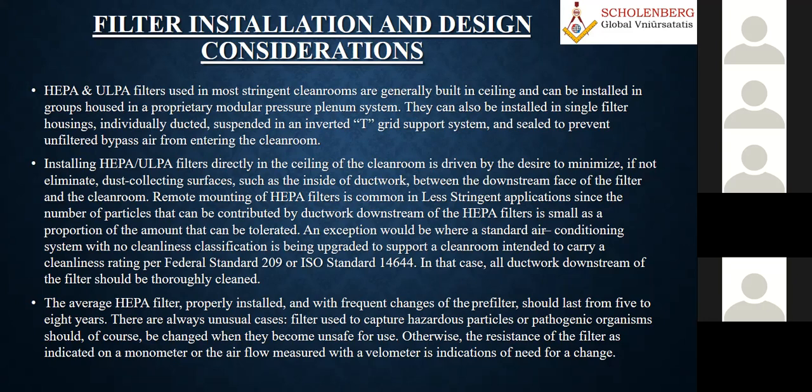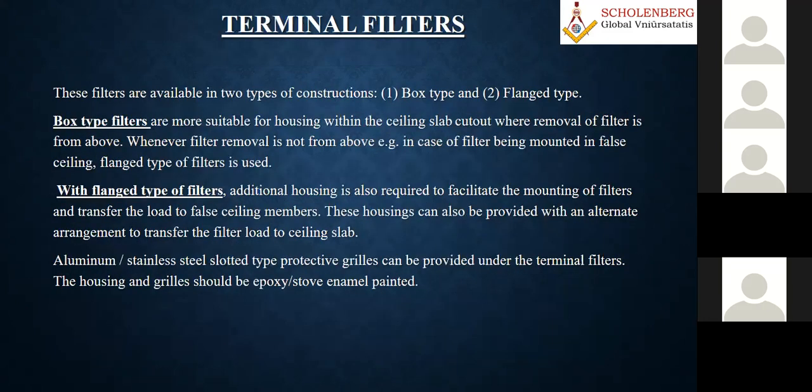So these all come in that. Some of the things are highlighted in this type of standard. So the average filters properly installed with frequent changes of the filter should last from 5 to 6 years life cycle. There are some filters, if you are exposed to hazardous particles like laboratory and pathogenic organisms, of course we have to change very frequently. Even in the hospital, normally, when we have HEPA filters and the infection patient is removed, we normally don't even touch it.